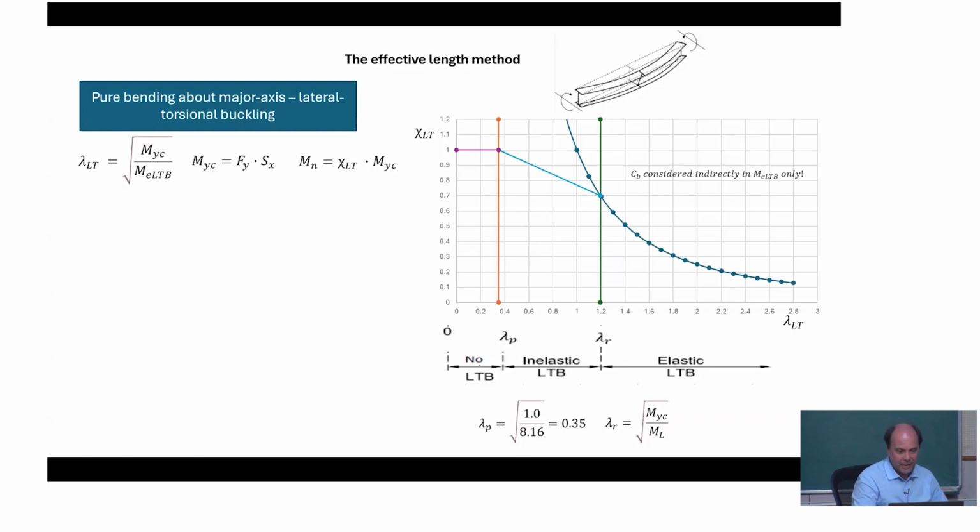Okay. So once we have drawn the LTB curve made of the 3 lines, this time already everything is defined in function of slenderness, so not on length anymore, but based on slenderness. It's almost fully identical to the length-based definition. And then what remains is very easy. Again, as I have shown at the beginning, that was the flexural buckling calculation. We know the slenderness, we know the reduction. Again, we do the same.